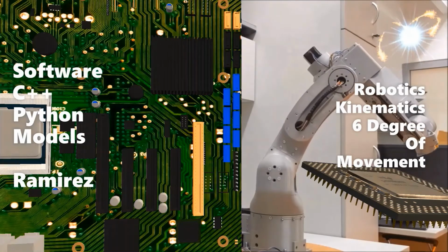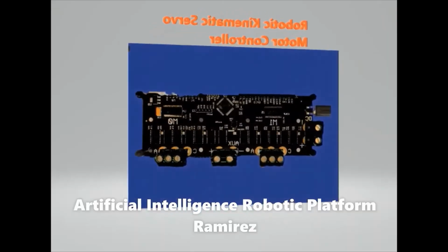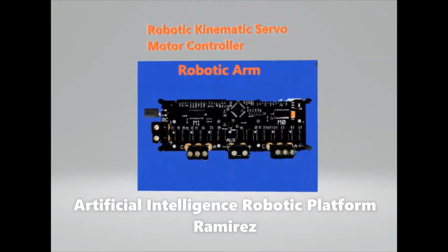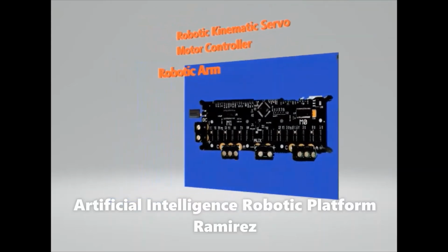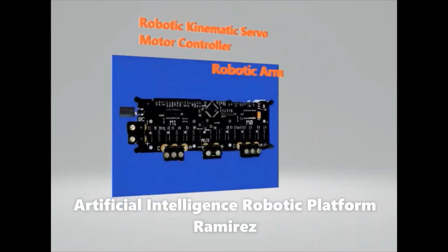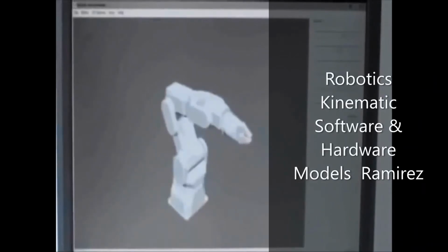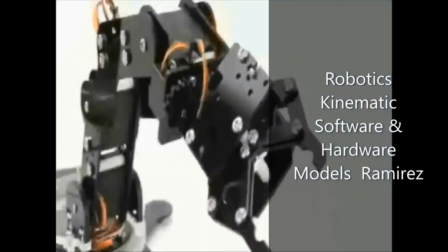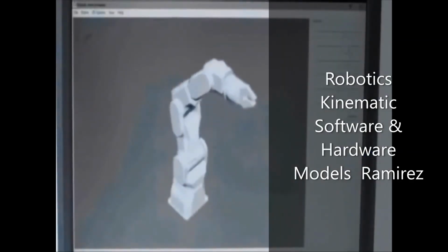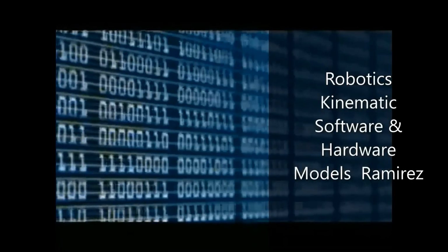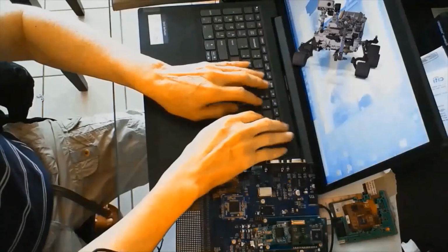The Industrial Robotic Arm Project is a modular system consisting of 6 rotary joints plus the end effector, which is a grip. The rotating joints consist of 1 joint for base rotation, 1 for shoulder rotation, 1 for elbow rotation, 1 for wrist rotation, and 1 for the grip rotation. The 6 servo motors are selected based on their torque for proper operation.